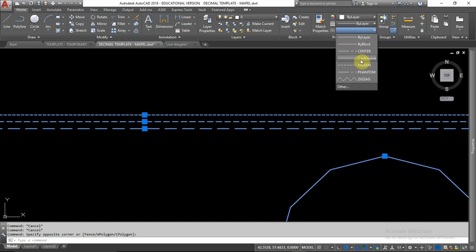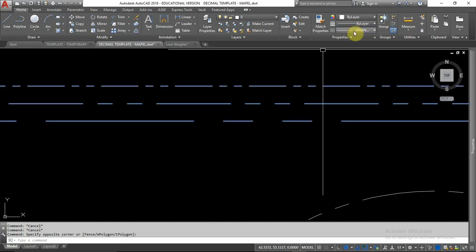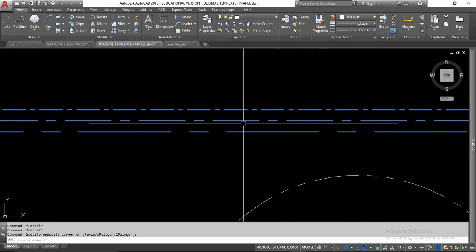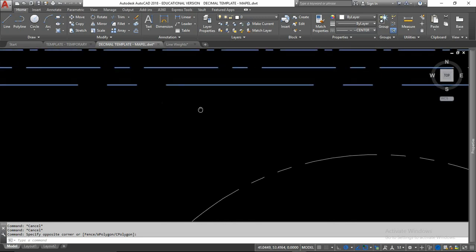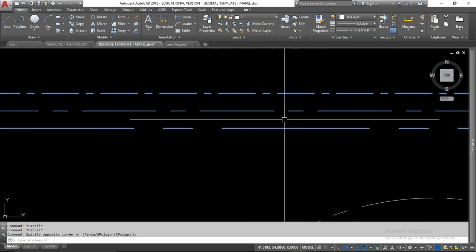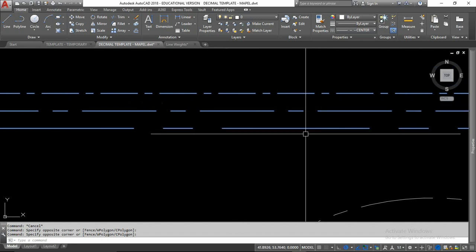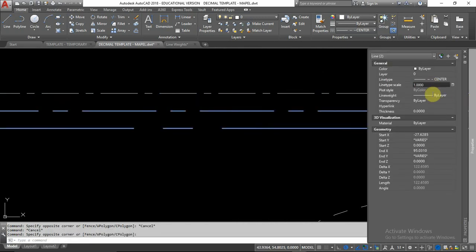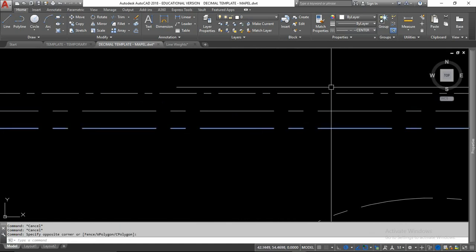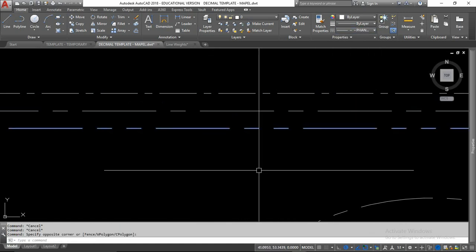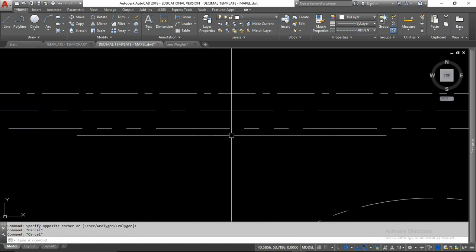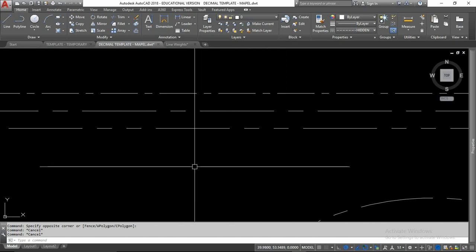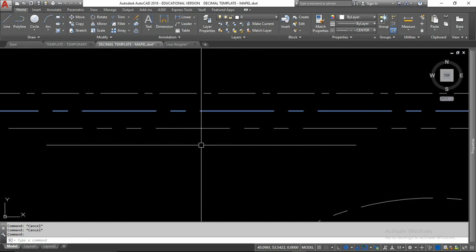So now I can say, no, I want center, a long line, a single dash, a long line, a single dash, or a small dash. And I say single. I'll just select those two, say those are one scale. The reason for that is a phantom, as I started to tell you. A phantom line is a long line and then two dashes. Long line, two smaller dashes, as opposed to a center line, a single dash.